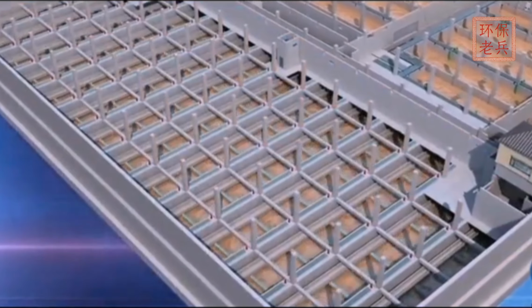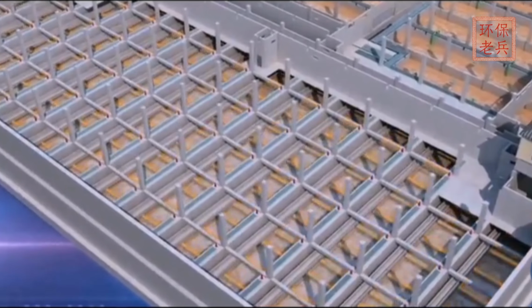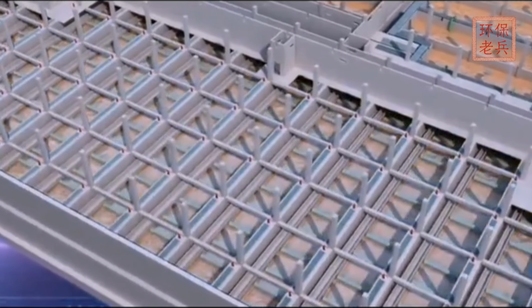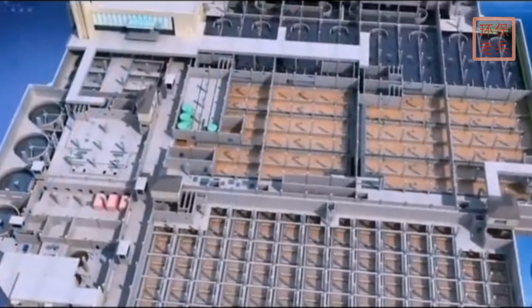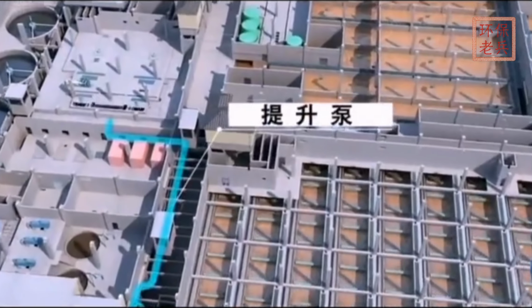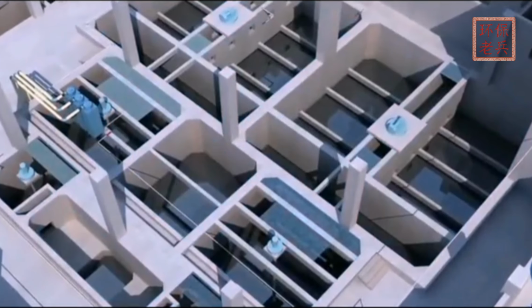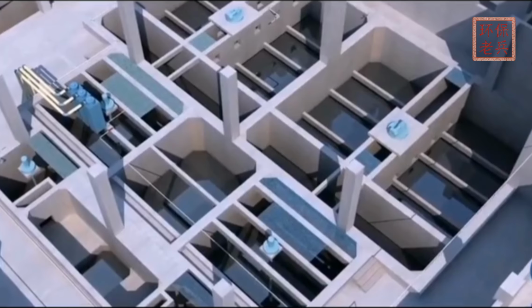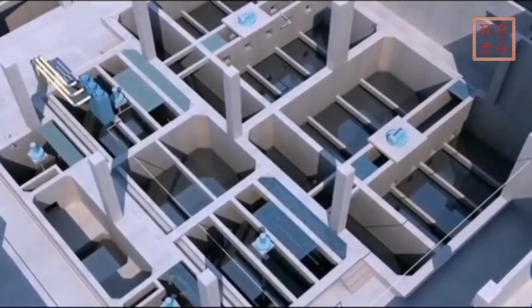The mixed liquor from the biochemical tank flows into the secondary clarifier, which accelerates sedimentation and forms sludge. The sludge is scraped by a scraper into a discharge channel and then conveyed to a sludge thickening tank. The clarified wastewater from the secondary clarifier is collected and lifted by pumps to the high-efficiency sedimentation tank.